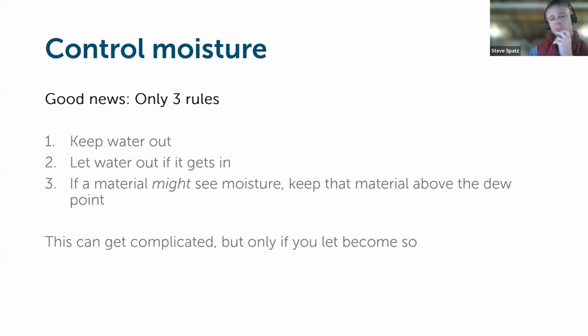So our options to keep this from happening are to, A, keep that moisture out, manage indoor relative humidity with mechanical ventilation. If the water and moisture vapor does and will get into those assemblies, you need to give it a clear pathway that it can dry outward to. And with the Zip sheathing there and the Zip bar, or any sort of low permeability exterior surfaces or sheathing on a building, you need good drying potential back inside to allow for that to occur.